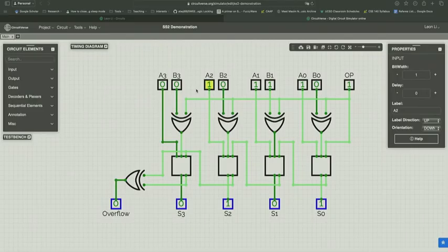There's a shortcut that you can use by only checking the carry in and carry out from the most significant bit. And that allows you to use a 2-input function to implement the overflow detection. So when you have 0, 0, 1 on the most significant bit, this is a bit of a hint for today's workbook. 0 plus 0 gives you a 1, and this is an overflow condition. If you look at the carry in and carry out at the most significant bit, in this case the carry in is definitely a 1. 1 is the only way to give you a 1 over here. And carry out would be 0. So they differ.